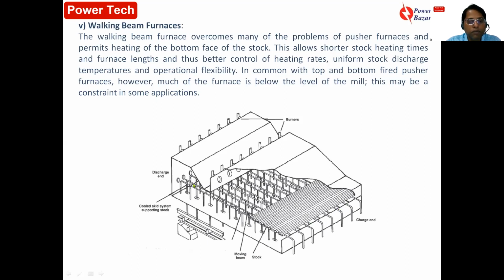So these beams, particularly the movable beams, are connected at the bottom like this. Now, if you see, there is a roller. Here this roller operates on a tapered platform. So what will happen when a motor moves this roller? This movable beam goes to the top, means height increases, so it takes all the materials, and as it moves forward, this movable beam walks and carries the stock.